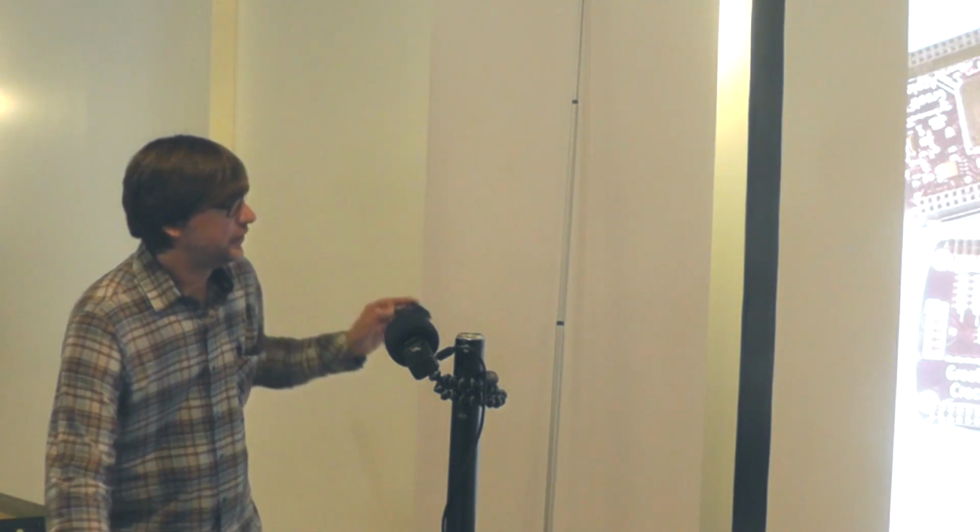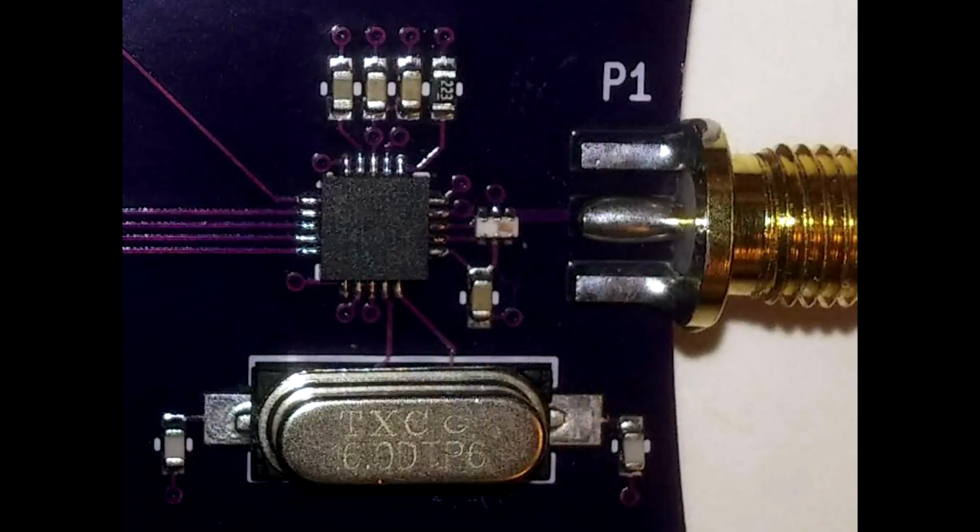I'm going to zoom in on this board. Actually, I'm going to zoom in in the future also, because I'm going to change to a newer rev of the board, the one that I just got, that has this SMA edge connector instead of the other connector we saw there. This is the entire RF section of this board. We have the NRF24L01 Plus, which is one that was mentioned in the slide I had earlier with different RF transceiver chips. It's a very popular 2.4 gigahertz transceiver chip from Nordic.